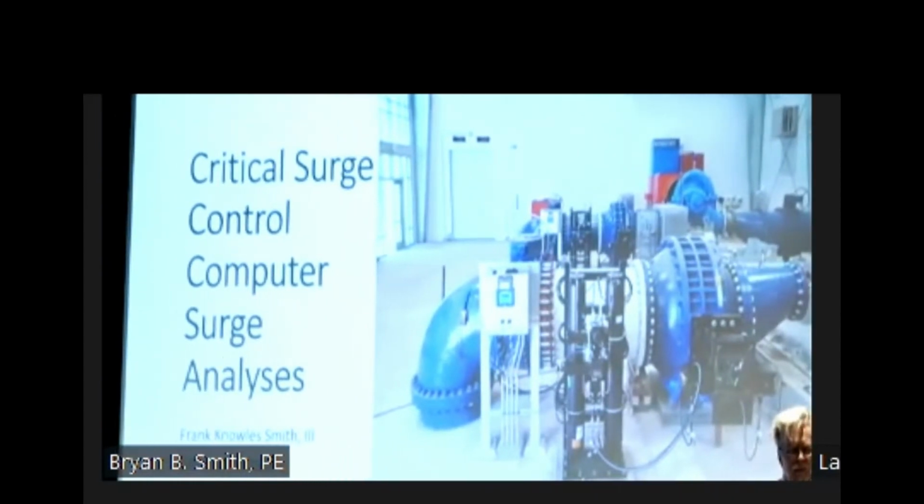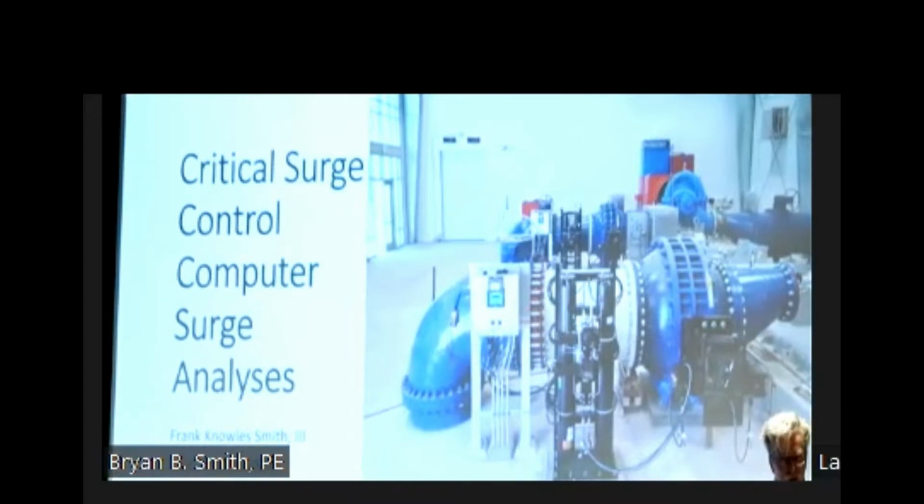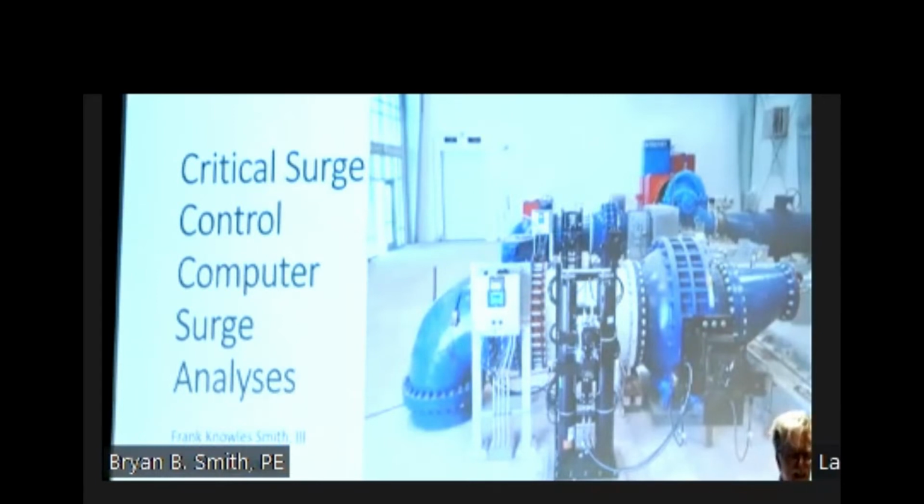I have a partially filled line, it starts to rain, filling up my piping system. I have some trapped air in there. That air pocket collapses, accelerates, moves, and is creating pressure transients or surges. So I'm getting these geyser flows in my drainage system, and it's devastating.